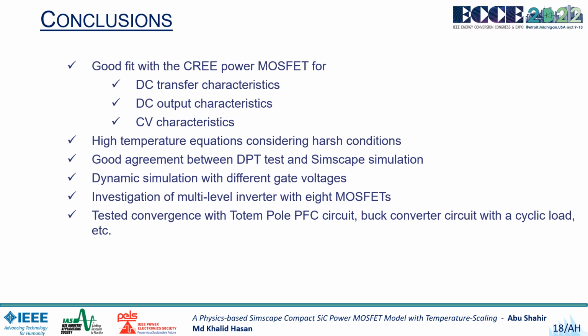The DPT test also shows good agreement with the Simscape simulation, which proves dynamic validation. The silicon carbide model has responded well in dynamic simulation with different gate voltages. The Simscape model has worked successfully in different circuits with built-in control systems in the MATLAB Simulink environment.